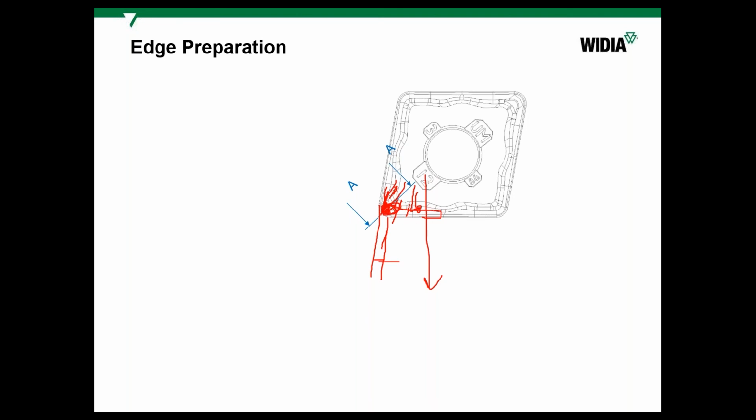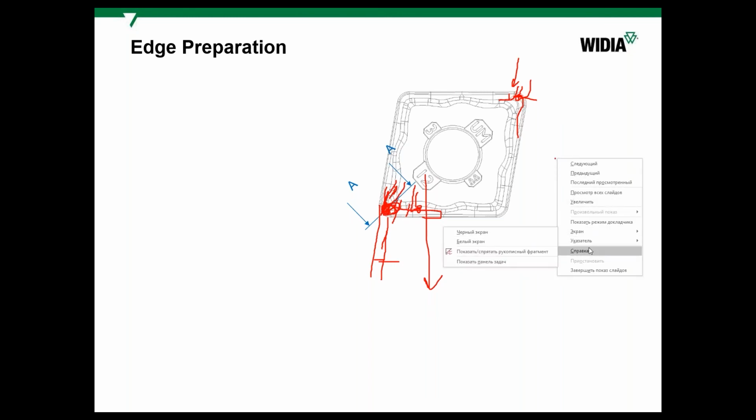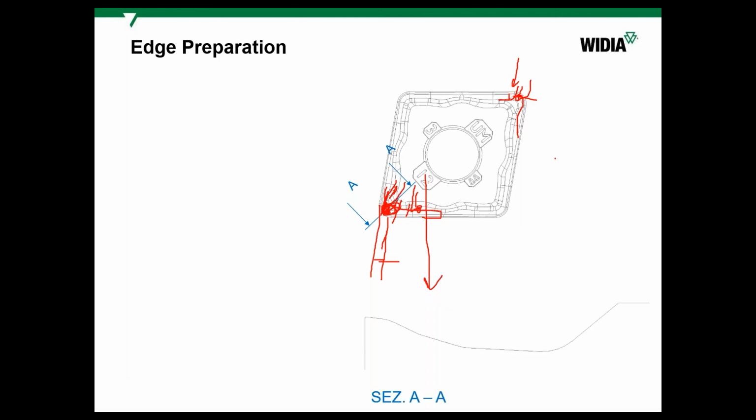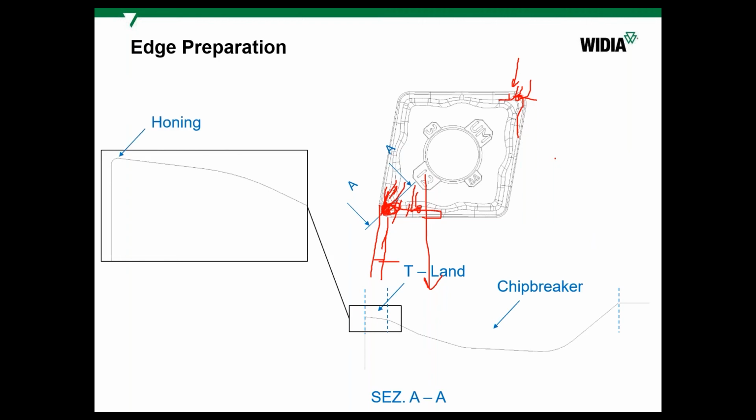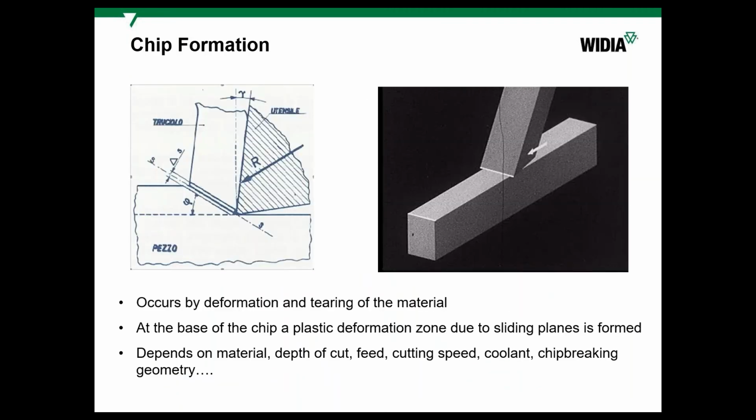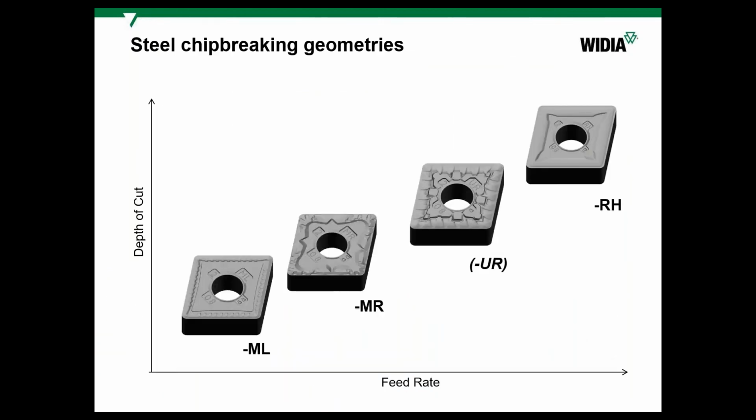That's what I can say now, and you can find the problems. That's why for finishing, the chip breaking profile comes closer to the corner, in order to avoid such situations. So in order to have this barrier, this perpendicular barrier to the chip, and a more or less developed chip groove. Yeah, this is the answer. I hope you got the point. If you have other questions or wishes, please let us know.